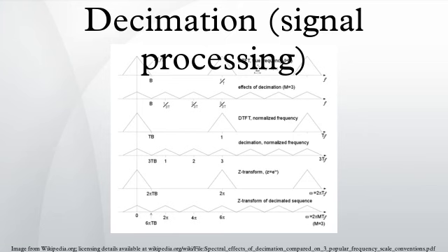In general, decimation reduces the data rate or the size of the data. The decimation factor is usually an integer or a rational fraction greater than 1. This factor multiplies the sampling time or, equivalently, divides the sampling rate. For example, if 16-bit compact disc audio is decimated to 22,050 Hz, the audio is said to be decimated by a factor of 2. The bit rate is also reduced in half, from 1,411,200 bits to 705,600 bits, assuming that each sample retains its bit depth of 16 bits.